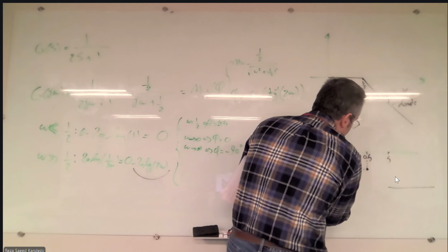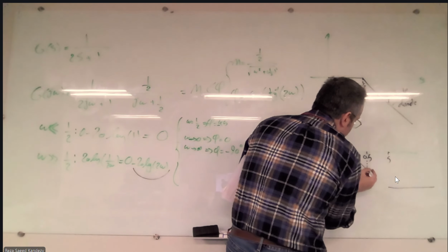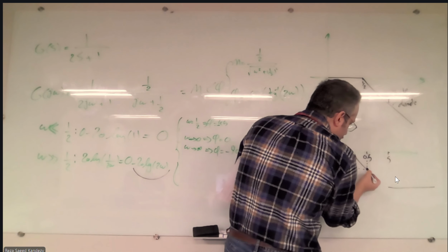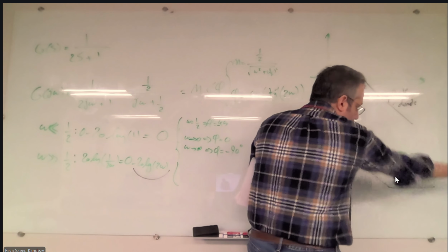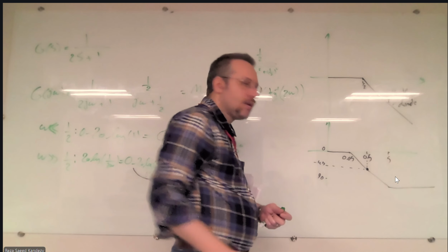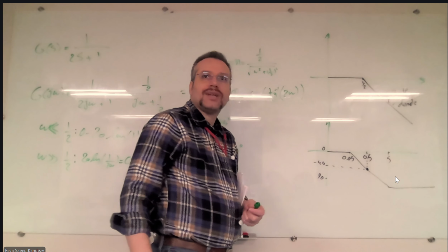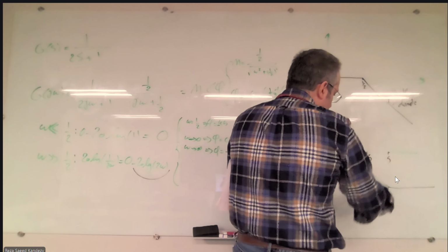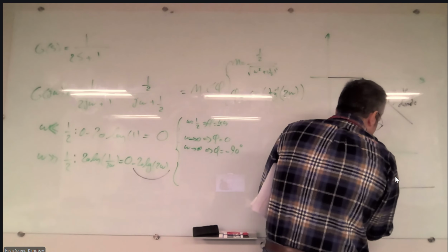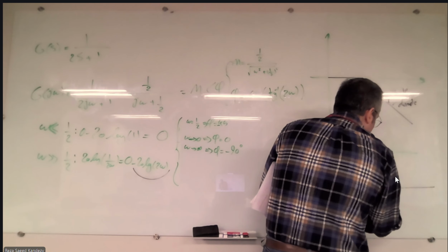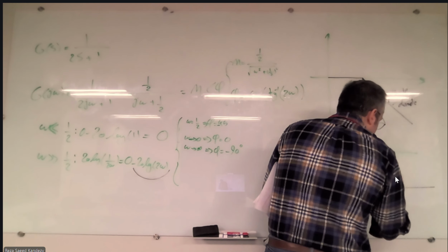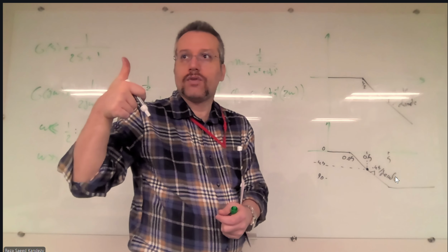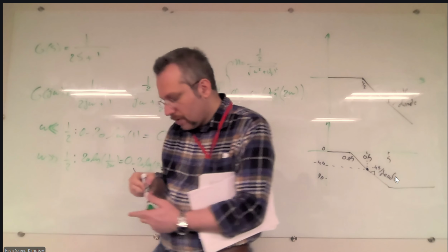So it is going to start here, has the value on the cutoff, which is 1 over 2, and then reaches the other asymptote at the decade after the cutoff. Now, you can imagine, and it is obvious, that the slope of this line is minus 45 per decade. Are we good?